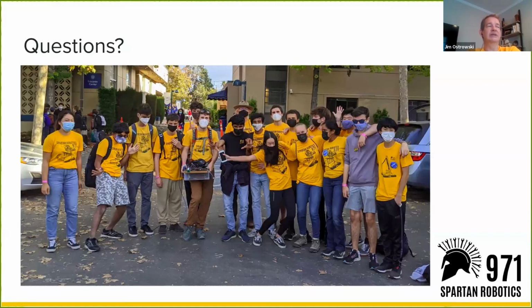What I do know about the 2019 vision system is that it used a more traditional method, which was projected light, so a flash of light with the reflective targets, and extracted the location of the reflective tape, and did localization there relative to the target.